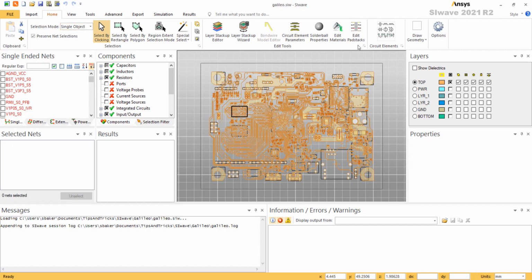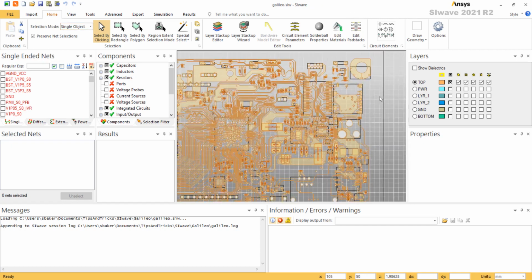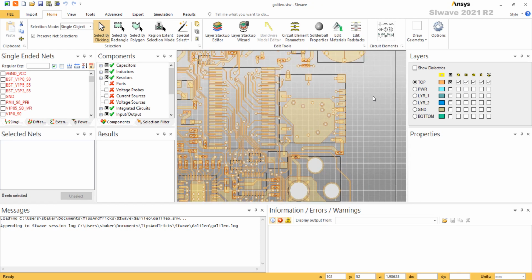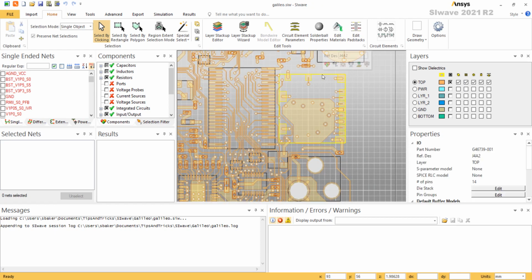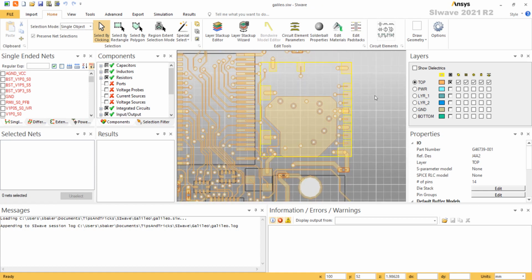Notably, with something like an ODB++ file, sometimes you'll see a component footprint that picks up more pads than there should be for that particular component. Let's say, for example, this I/O device has a few extra pads, like say these three on the end, and we just wanted the component footprint to span all of the other pads.